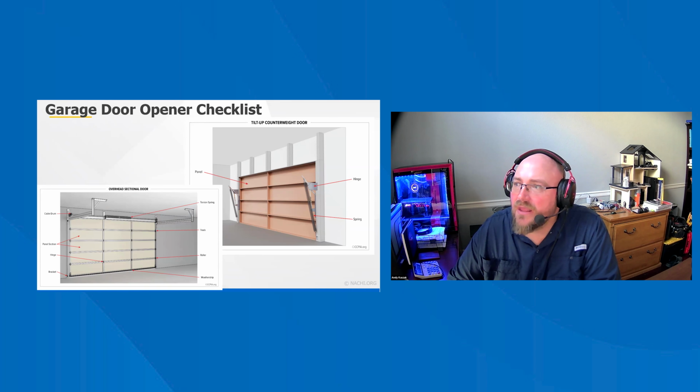Springs and hardware. If a spring is broken, operating the door can cause serious death or injury. Do not open the door if there is damage. Visually check the door's hinges, brackets, and fasteners. If the door has an opener, the door must have an opener reinforcement bracket that is securely attached to the door's top. The header bracket of the opener rail must be securely attached to the wall or the header using lag bolts or concrete anchors.